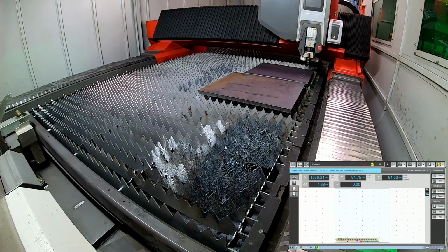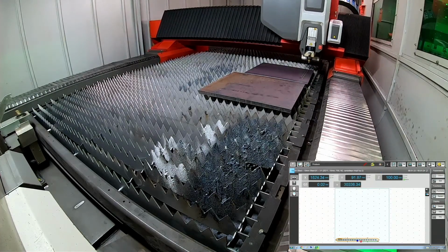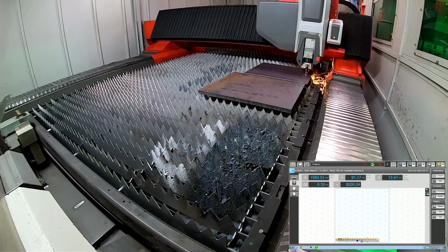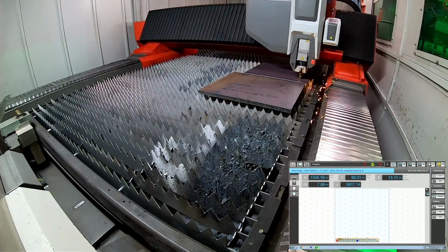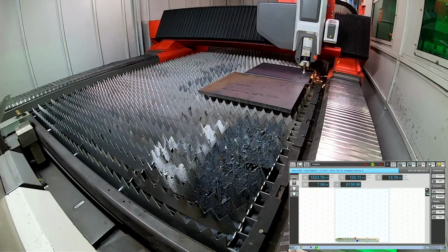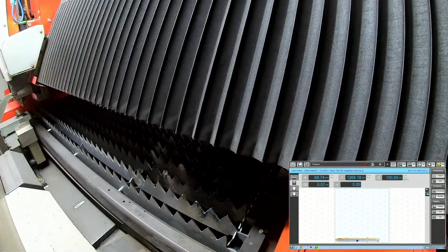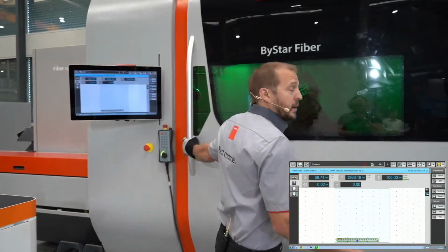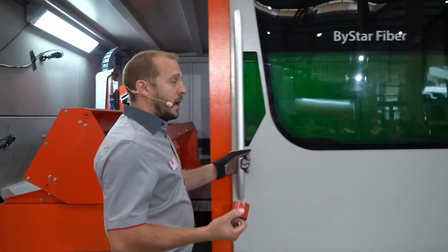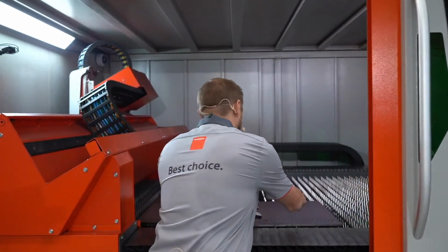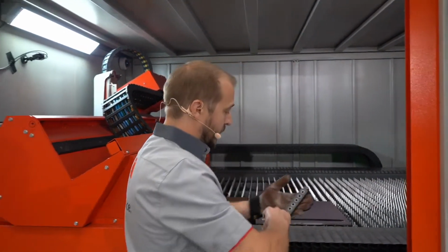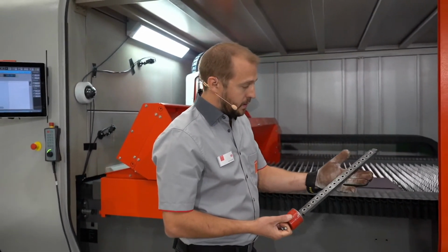So now that we are on the straight line, you can see we stopped. That's because the speed ramped up to 115% in this case. The ICP realized it, reduced 5% and continued to cut the part. Which means we cut this part with 110% of the nominal speed. So now we take out the part, perfect